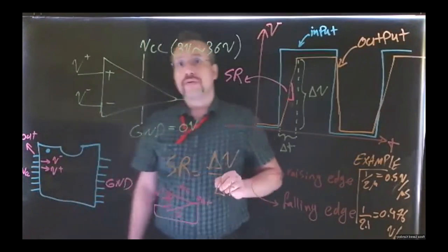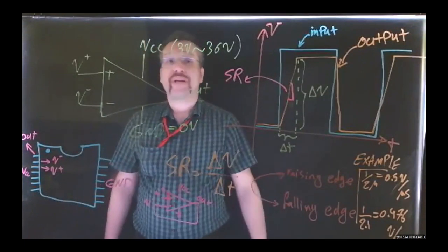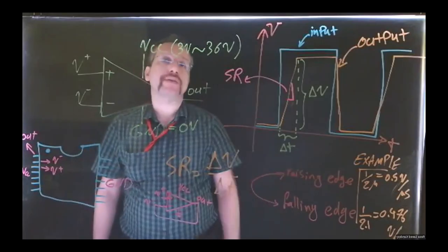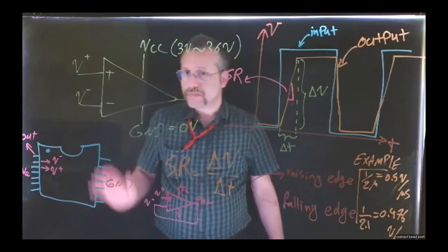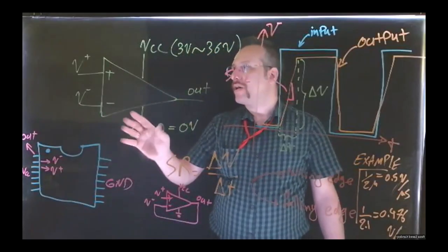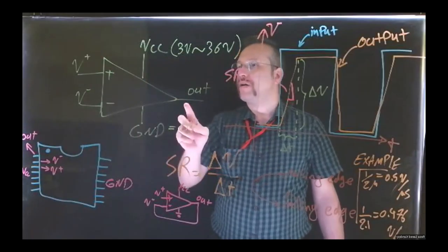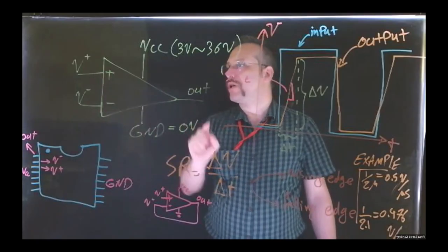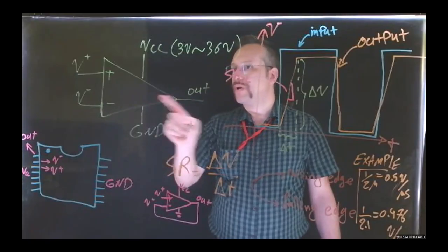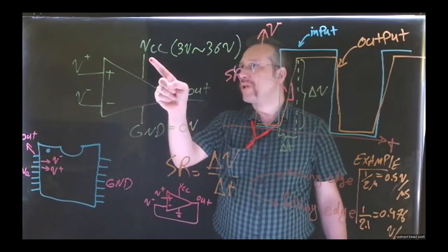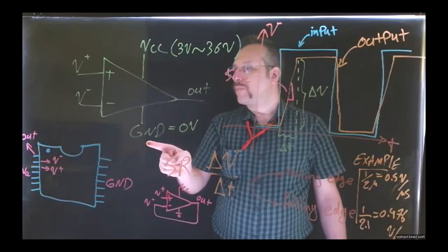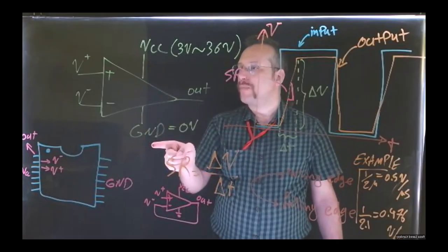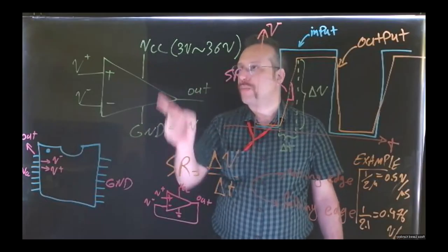Okay, now that we know how the op-amp works and what the applications are, and we went through the theory, let's talk about how we can measure the slew rate in the laboratory. Now, we already mentioned an op-amp has 3 main signal ports and 2 power supply ports. Okay, we have the non-inverting input, the inverting input, and the output. We have a port that we connect to the VCC and a port that we connect to ground. So these are the positive and negative ports of our voltage supply, our power supply.